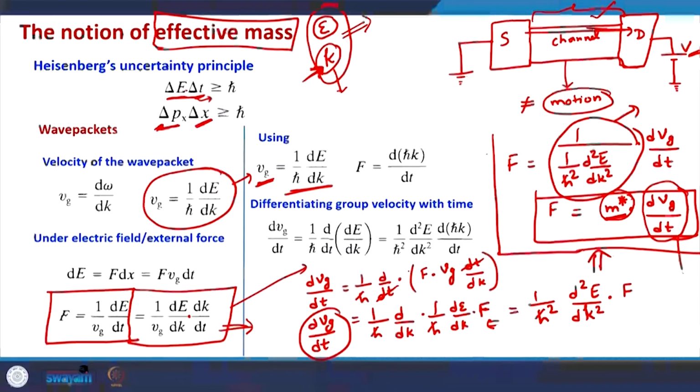Okay, so it is quite an elegant concept because it simplifies the understanding and the calculations. Instead of using the mass of the electron, we need to use the effective mass of electrons, and at many places we can still use our classical concepts if we properly define the group velocity of the electronic wave packet.